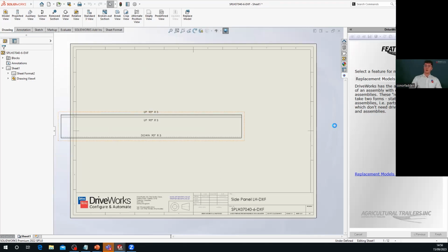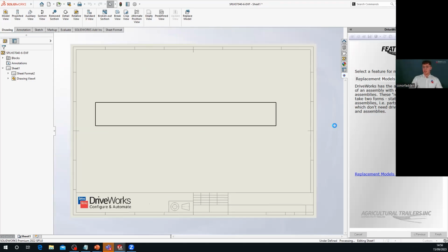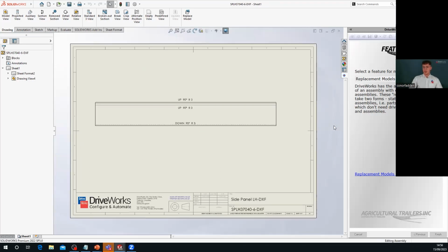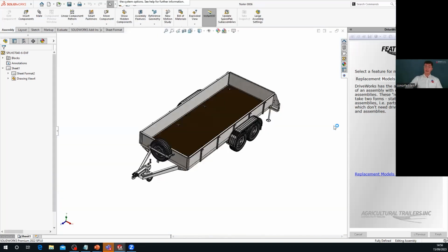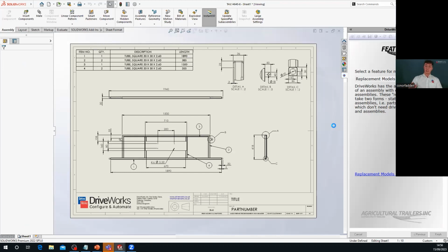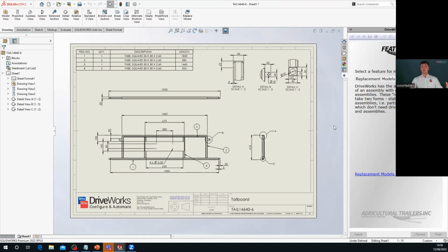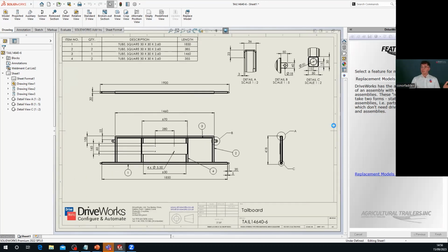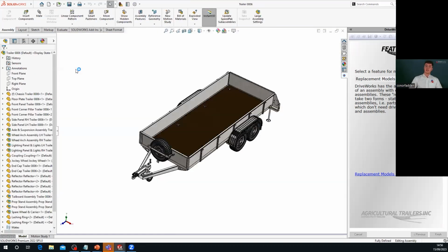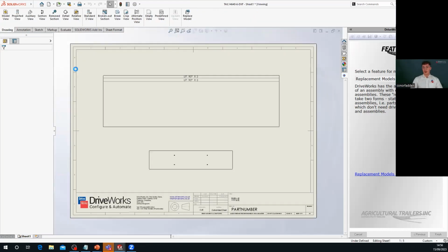Now, in this case, once we finish all of our design automation, which is exactly what it's doing, our design automation is going through anything that we've actually captured. So we've obviously captured all of these drawings against all of these parts to make sure it's all referenced correctly. We can then rescale, resize, reposition everything as you would relative to the parts, include bill of materials inside of each drawing, making sure that it has all of the correct dimensions, so that way it's all ready for manufacturing.